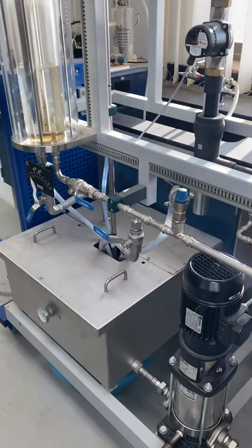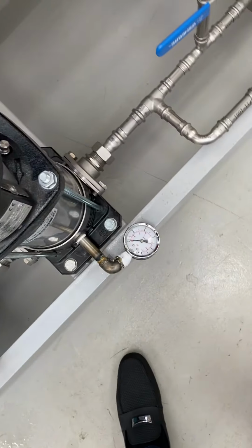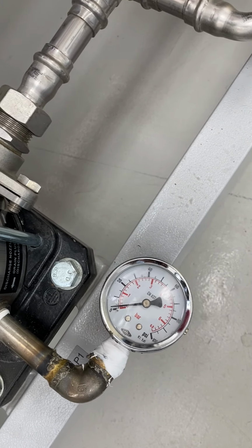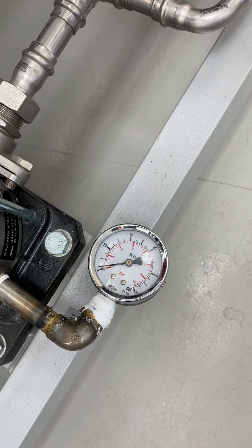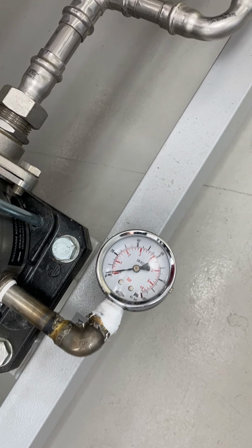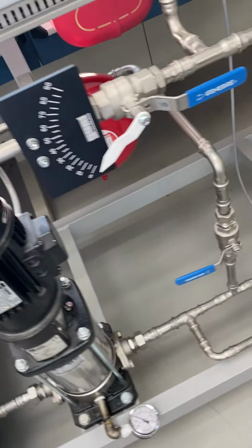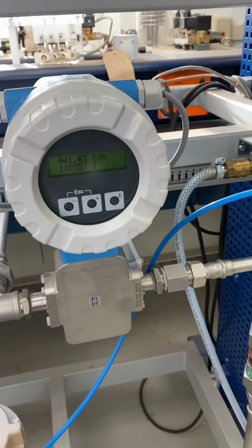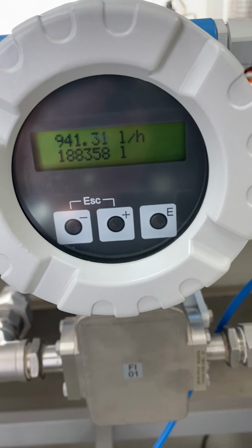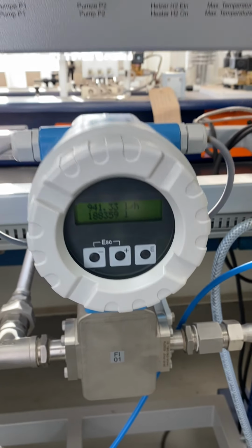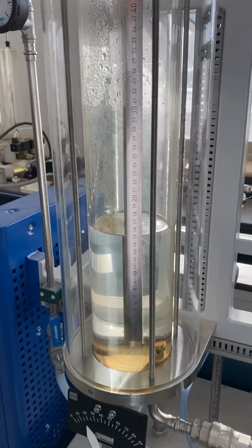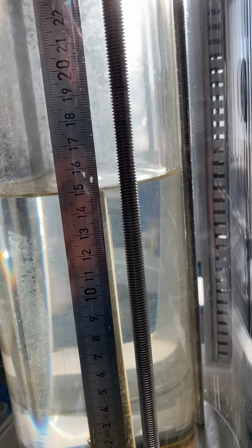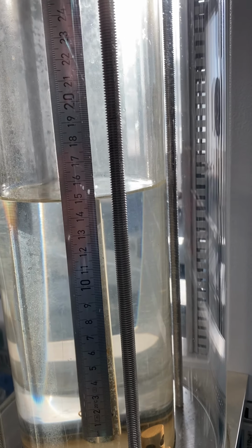Along with that, we have the P1 discharge pressure, and as you can see right now, compared to 6 bars in the flow experiment, discharge pressure is barely above 0.2 bar. Okay, so it's very likely to be around 0.3. The flow meter indication is somewhere around 942. We'll take an average value. Okay, this is a high sensitive flow meter, and liquid height is 15. It's showing 150 millimeters or 15 centimeters.